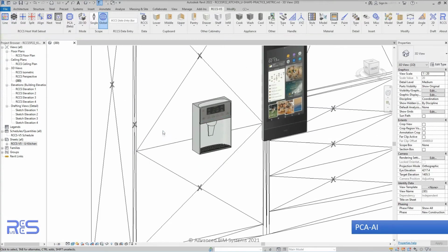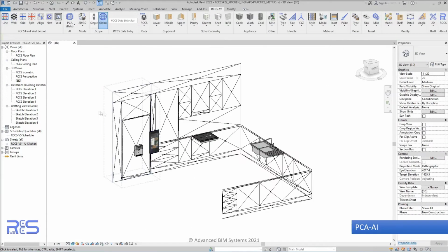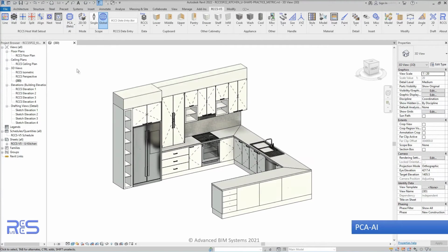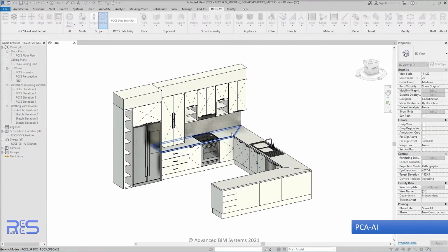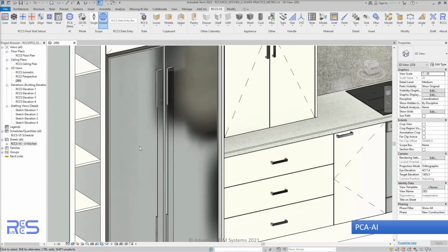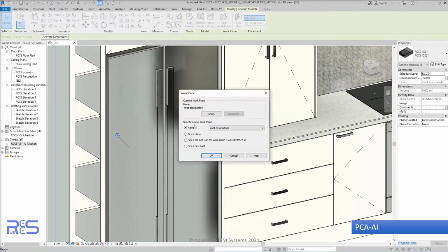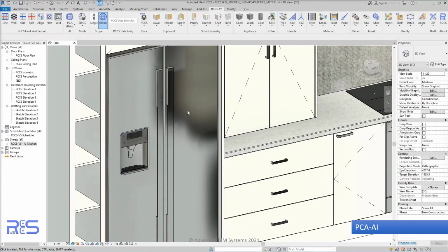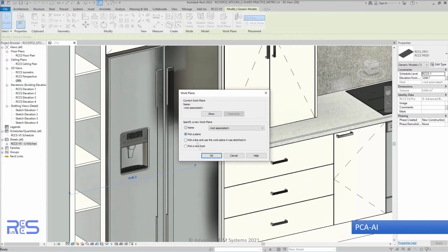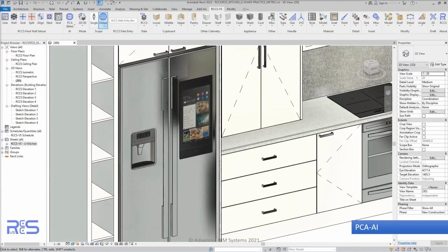Here we've switched back to 2D so that we can then begin removing grid lines by deleting the grid lines, and then telling it to switch back into 3D mode. You may find that switching from 2D to 3D does require that you go back through and join different elements. And in certain occasions where here we've modified the refrigerator, we might have to go back in and place the different components in their respective locations.